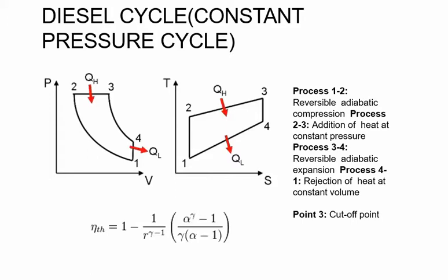During the top isentropic process, energy is transferred out of the system in the form of work out, but no energy is transferred into or out of the system in the form of heat. During the constant volume process, some energy flows out of the system as heat through the depressurizing process, that is Q out.